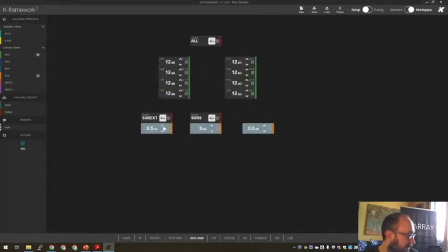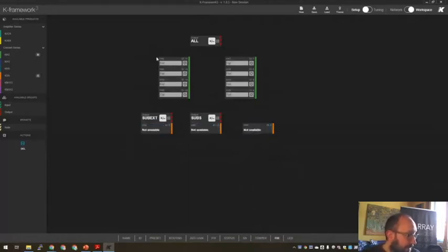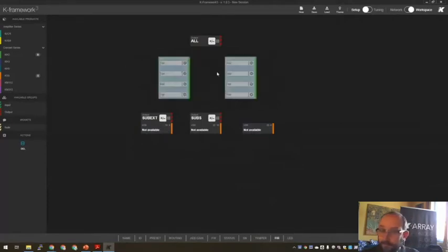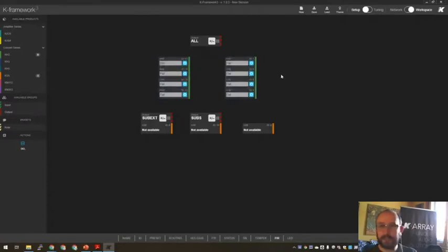This one is also useful, especially in the Mugello, if you want to play with the beam steering. So as soon as you uploaded your files, you can switch off the steering on the whole system just with 1 click. This can be useful for understanding if what you are doing with the beam steering is what you really want or not. So just keep the Alt button pushed and left click on the mouse. Now we have our system ready.